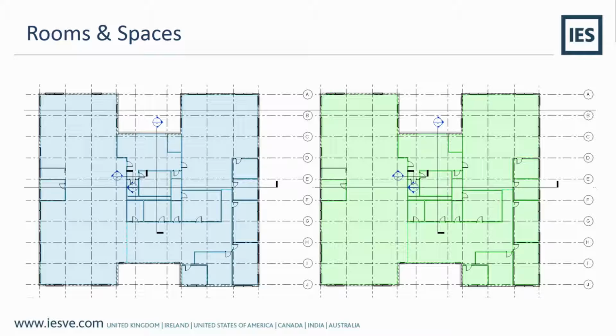The key one there when you're looking at Revit is whether you're using Revit Rooms or Revit Spaces. And when I discuss these today, although thermally, when you're building up your building design, zones do matter, with regards to exporting IFCs or GBXMLs, when you're looking at a volume, a room or a space, when I say them, I intend the same thing.